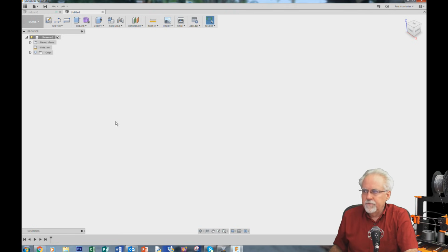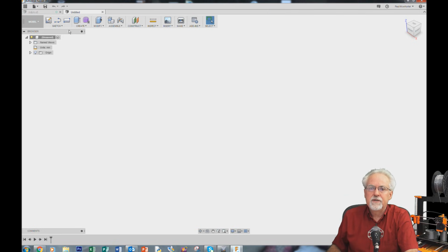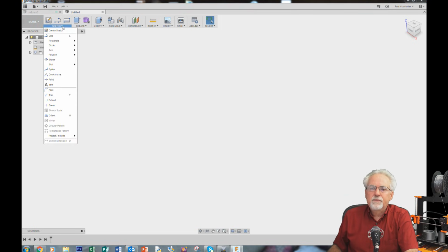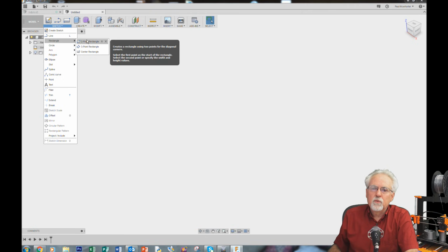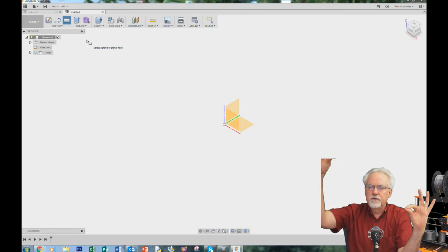Okay, so what's the first thing that we're going to do? We're going to sketch, which means we need to work with these tools here that are under sketch. So I'm going to click on that, and just click on it and let up, and then I'm going to come down. I want a rectangle, and then I want a 2-point rectangle. That's going to be from one corner to another.